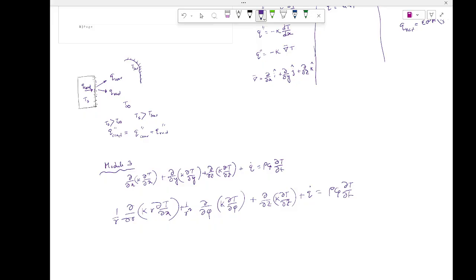I want everybody to be very comfortable with these two equations, okay? Once you have those equations, you simply apply the boundary conditions and the assumptions. The assumptions could be 1D, steady state, Q dot equal to 0, and constant properties. There are 4 assumptions that can come up here. Right, Mitch? Remember? 1D, Q equal to 0, what else?